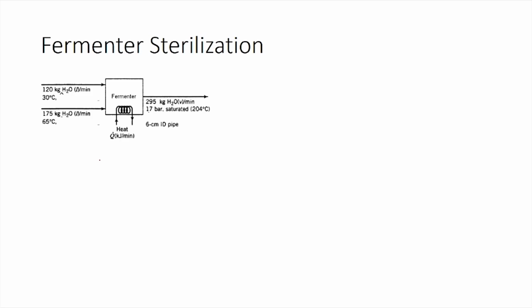This being an open system, the general energy balance equation would be delta H dot plus delta Ek dot plus delta Ep dot equals Q dot minus Ws dot. Now, we cannot ignore the kinetic energy term because only the inlet kinetic energies can be ignored. So, we have to calculate the outlet kinetic energies. So, this term would exist. Obviously, delta H dot will exist because you have change in enthalpy due to phase change and also due to temperature change.